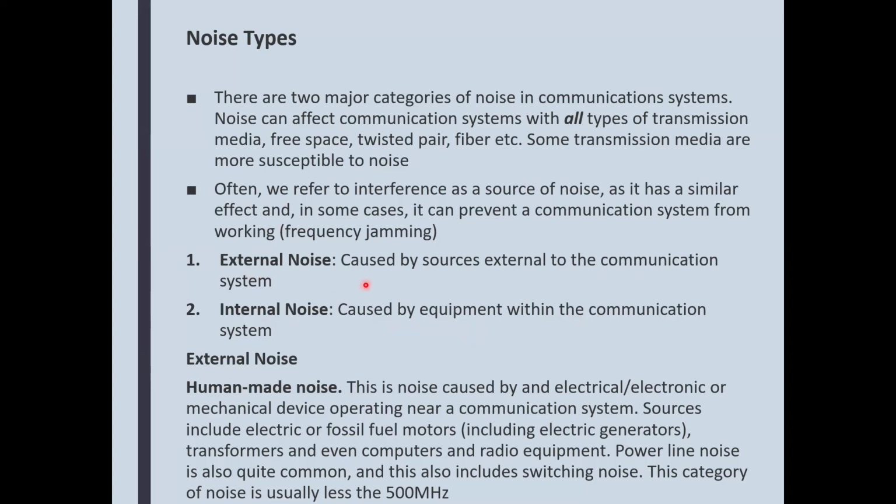So external noise, let's say you are going to install data wires close to fluorescent lights. There's noise from the fluorescent lights or the alarm system or fire alarm. Those are the biggest noise makers. The cables or a thermostat also create a lot of noise.